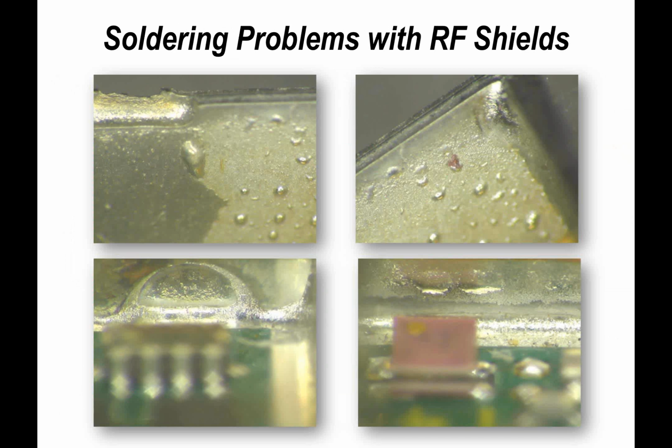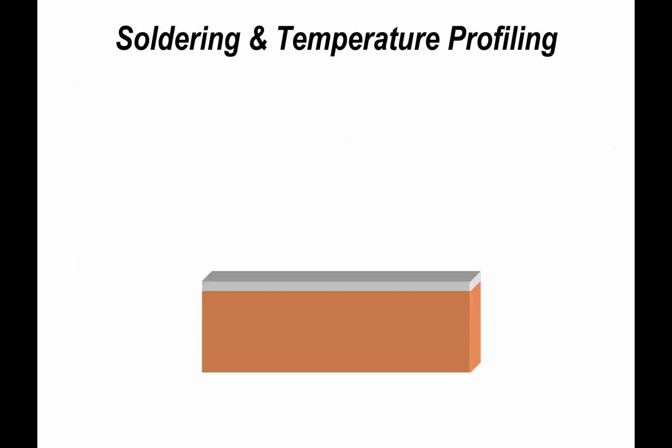A lot of people forget that plating can outgas and cause pimples and voids on surfaces, just like a solder joint. So don't always blame the materials. Quite often it can still be other surfaces which have an impact. It really is a cosmetic issue, but when you look at it for the very first time, it's not very attractive on these heat shields.